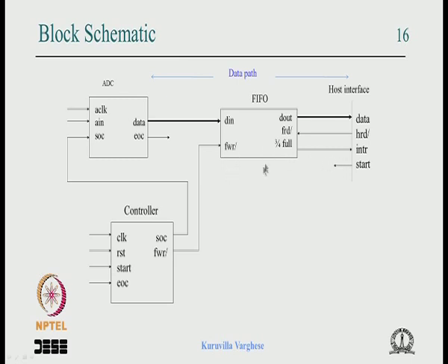And maybe the last time, when the host stops it, there is some data remaining there, we do not know how to empty it unless there is another handshake signal. So maybe that is okay, like you say stop, you remove the start, then the interrupt comes or does not come, some data may remain there, it is okay, we will lose some data at the last cycle.